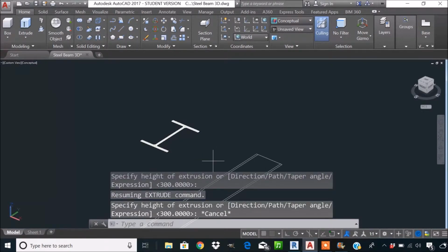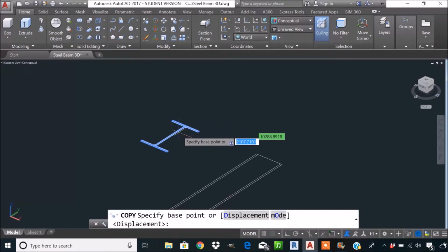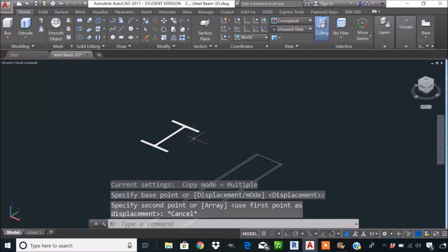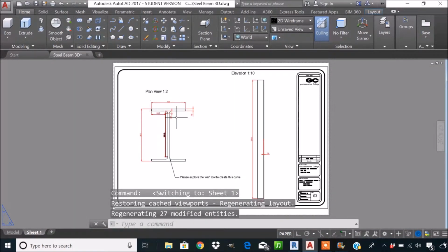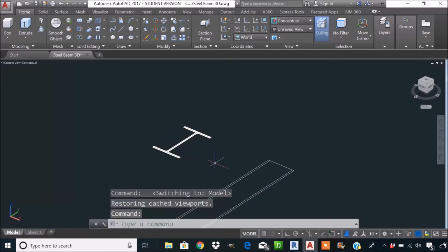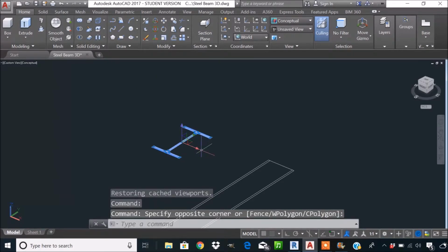So because we're using that shape in our plan view, why don't you make a copy of it? Because if you see in paper space, we're using that in that viewport, so we want to copy it. Now here's where it gets interesting in CAD, because you're working in 3 dimensions.